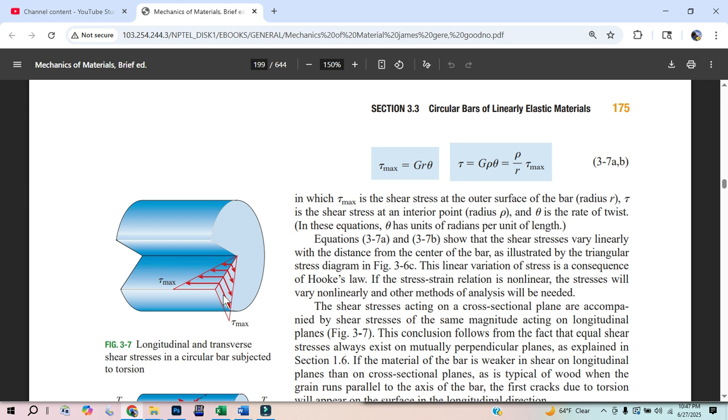Okay, so a few things pop up when we talk about torquing or torsion, torquing a shaft and twisting it. One is that we're no longer pulling in tension or pushing in compression on something. We actually are shearing. And so we have to understand that when we shear, we are sliding two pieces of material across each other, and it's the area in between those two pieces that is holding the strength. I think that's kind of a decent way to explain it.